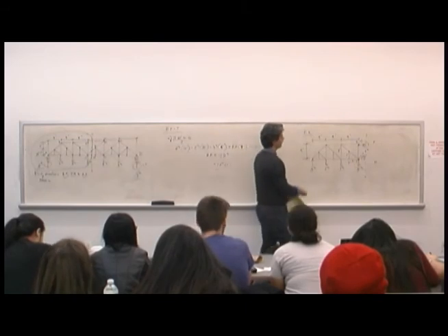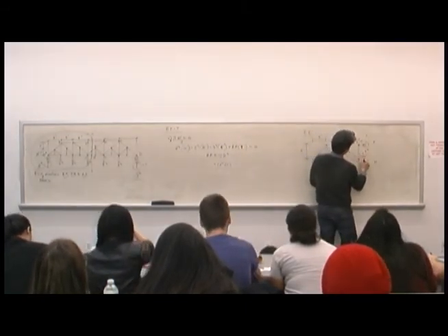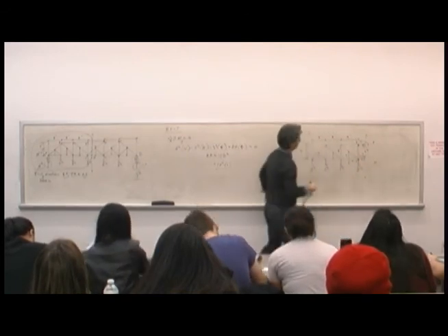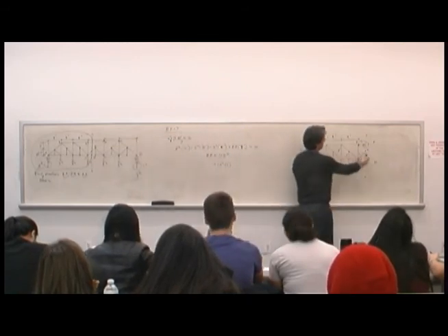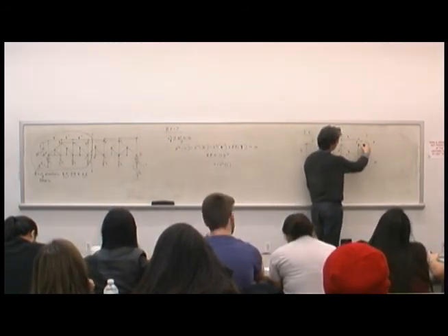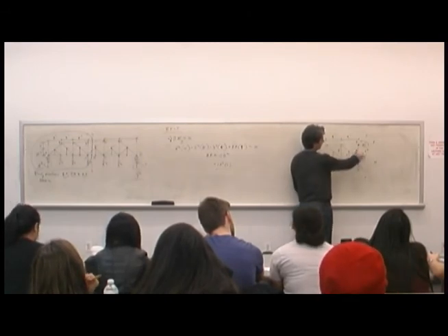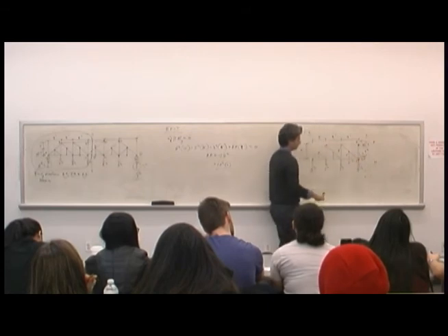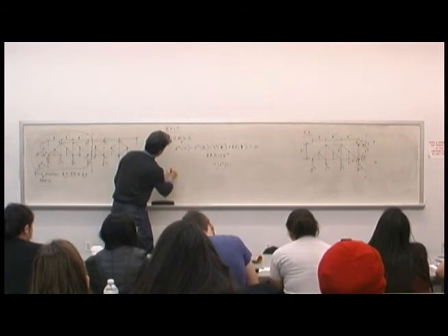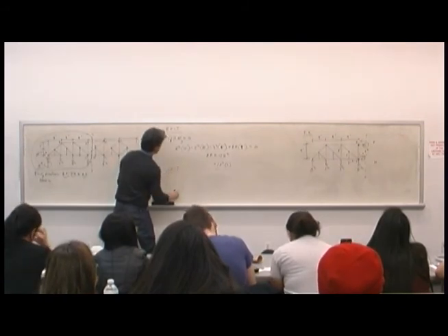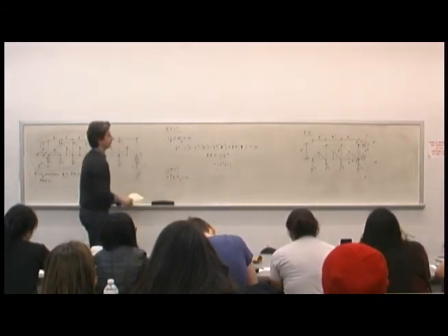I need the components, right? I need the components of JK. I need something like that. But I don't know anything else horizontal with this. I have all this that's vertical. So if I balance everything in the vertical direction, I could solve for that one force. So looking for JK, sum of the forces in the vertical direction.